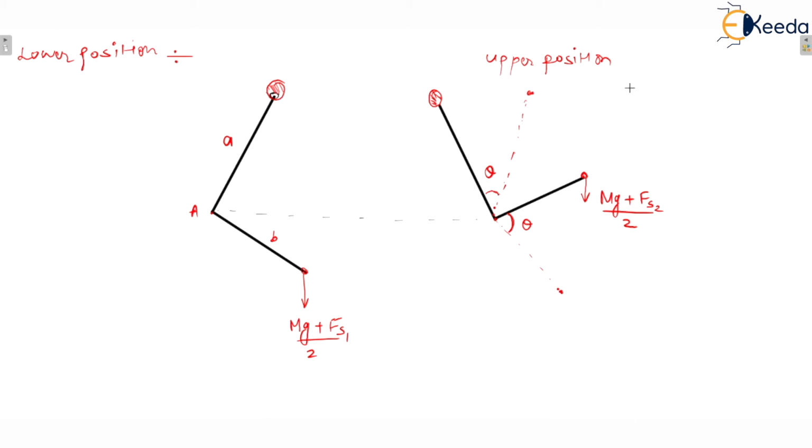So let us consider that this is the sleeve axis. This is the radius of rotation R1 initially, and now the second time the radius of rotation becomes R2, so this becomes R2 minus R1, and we all know this is nothing but the sleeve movement.